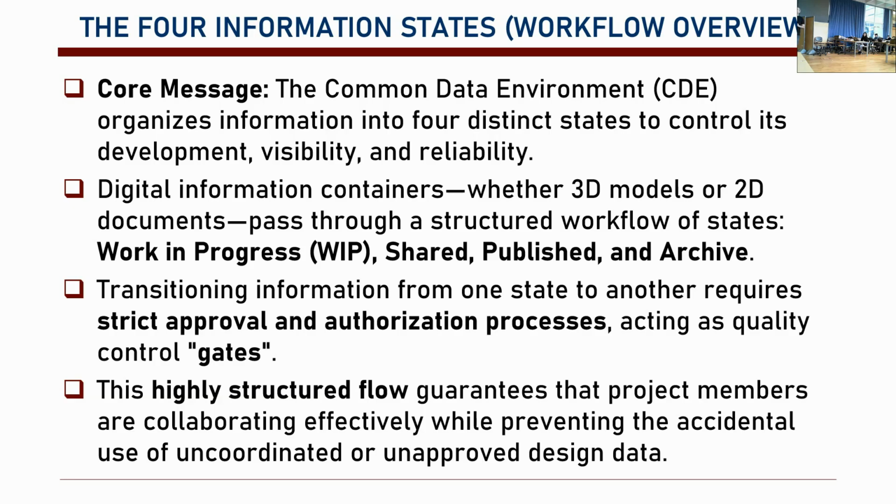So, from one stage to another requires strict approval and authorization process, which we call control gates. So the BIM manager makes sure that this work in progress can be moved to shared, or shared could be moved to published, okay, or archived. So it's a highly structured flow, so that members are collaborating effectively, okay?